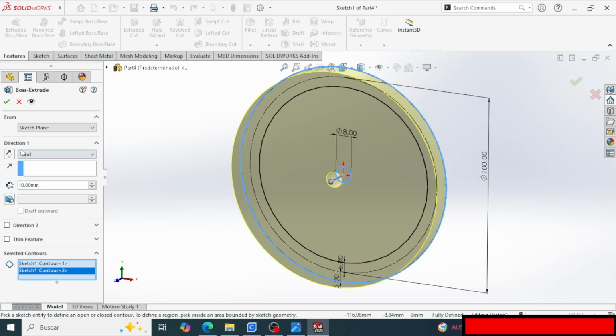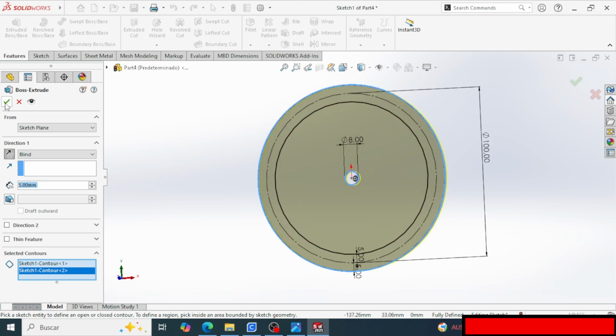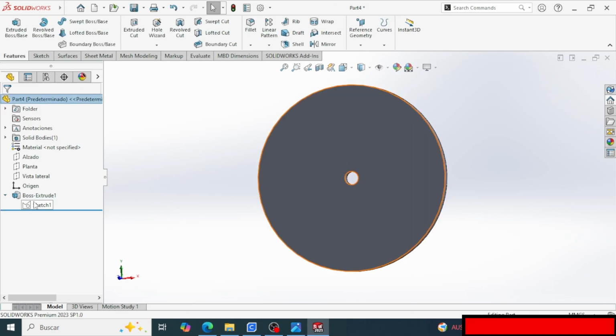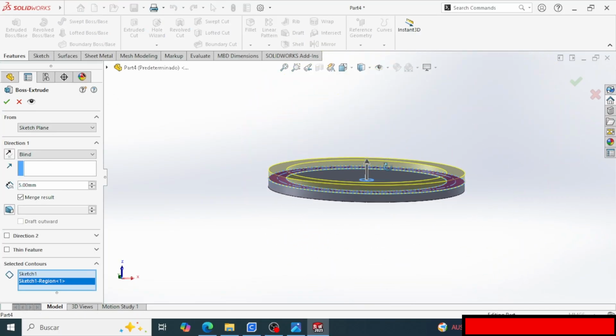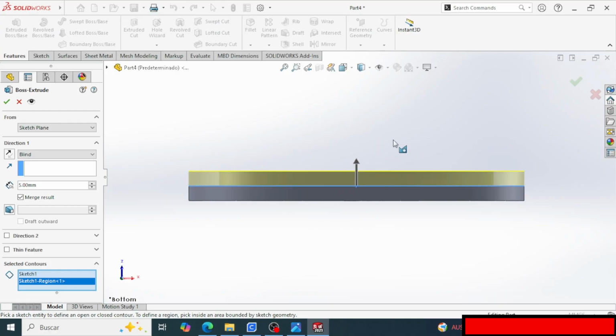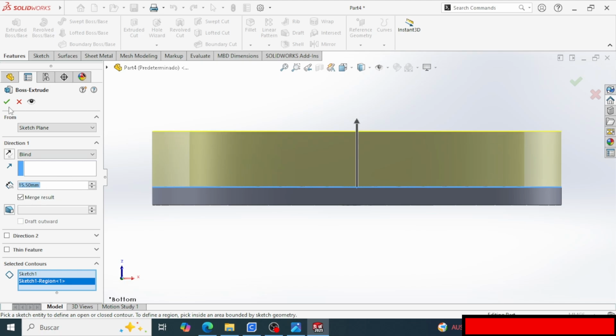This is going to be the base of the crown gear blank. I'm going to set this to 5 millimeters. And with the same sketch, I'm going to extrude this part like so. And we want to extrude the radius of the pinion gear. So 25 millimeters over 2. And I want a bit of clearance from the base of the gear. So I'm going to add to this 3 millimeters. Just like so.